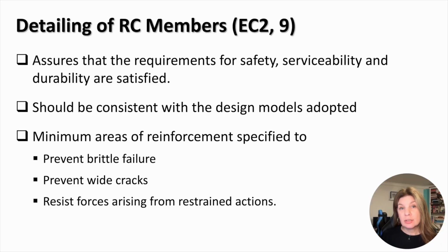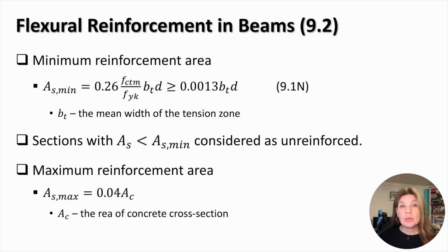Detailing should be consistent with the design models adopted for reinforced concrete members and should assure that the requirements for safety, serviceability, and durability are satisfied. Detailing requirements include minimum areas of reinforcement specified to prevent brittle failure, wide cracks, and to resist forces arising from restrained actions. Eurocodes limit the area of reinforcement in beams in a certain range that's defined by the minimum and maximum values.